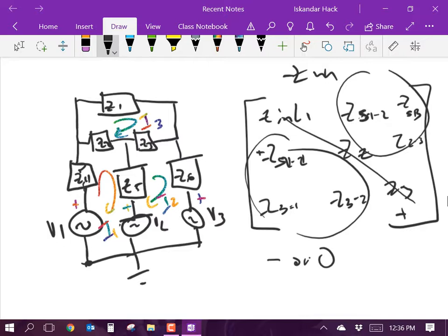You might find a weird case, but 99% of the time that holds. Also this is going to be a symmetrical matrix, because you can't have an impedance shared between loop 1 and 2 and an impedance shared between loop 2 and 1 that's not the same.